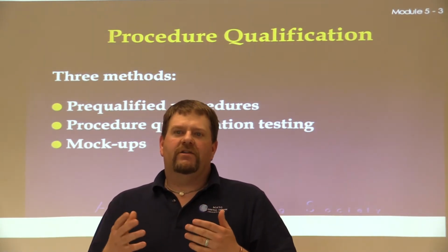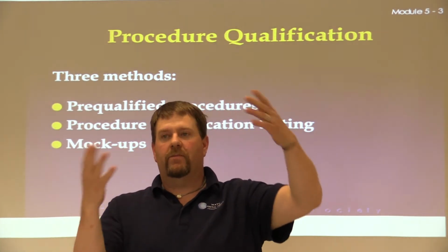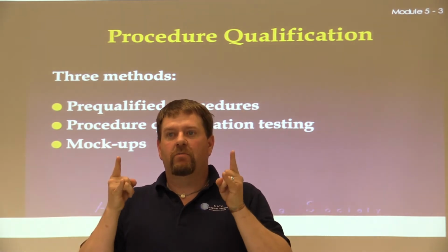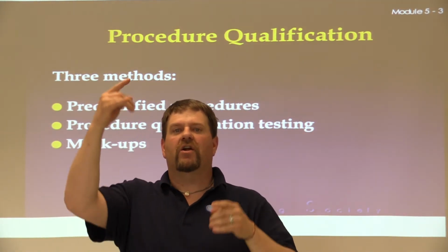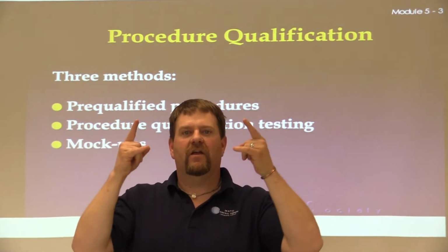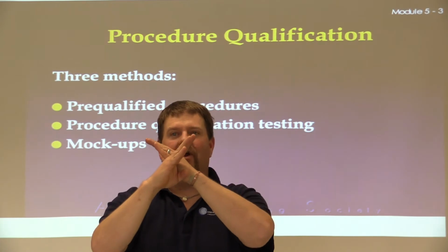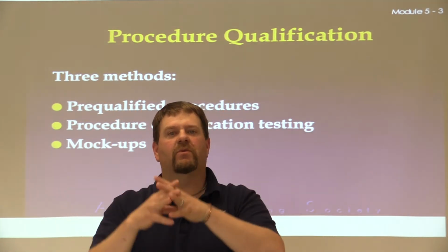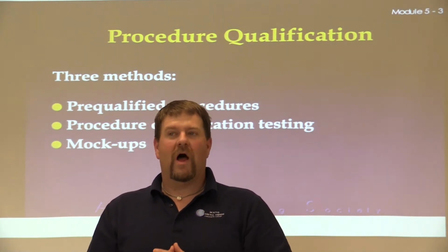Say I've got a T, K, or a Y, or a lateral. So it comes in, particularly on a crane. You have these large 4 main structures going up and down, but instead of pieces going just straight across, they're coming out at different angles to help support each other, right? And most of you have seen a lattice crane, or a power line that has crisscross members within it. Usually those are what we refer to as a T, K, or Y position.